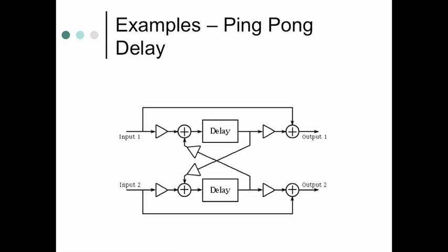capacitor that basically has two plates that don't ever touch each other, two metal surfaces that don't ever touch each other. When you try to put a voltage in, it's going to fill up the plate with charge and induce a charge on the other plate, but no current can actually flow through. No electrons can actually jump over and go through, right? So if this was direct voltage with no frequency at all, this would be like infinite resistance because nothing could get through. It would be like two different wires that don't ever touch.